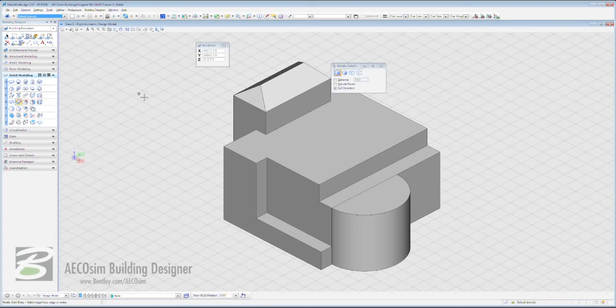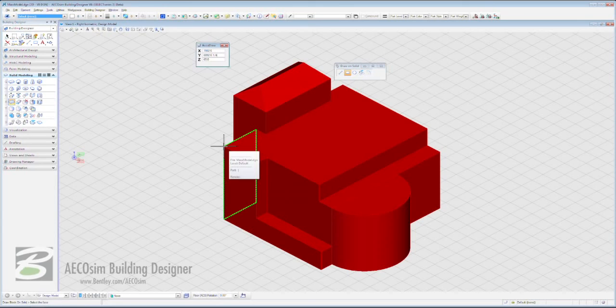But it goes further than that, because if we come back to push-pull modeling, we don't just have to draw lines, we can actually draw shapes as well and use those to impress. So what we can do here is we're going to come here, we're going to come to this elevation here, and we're going to offset it, and we're going to offset it by 2 feet either direction. And now what we can do now is just draw this onto our shape.